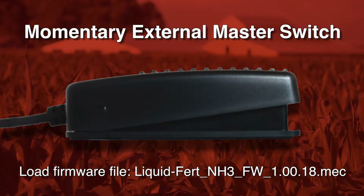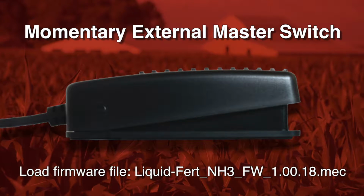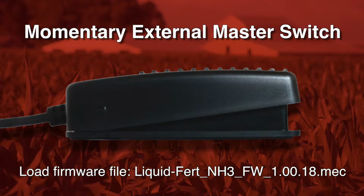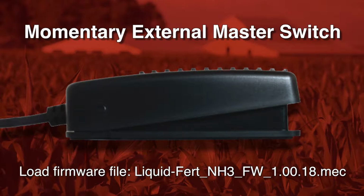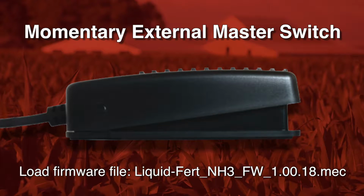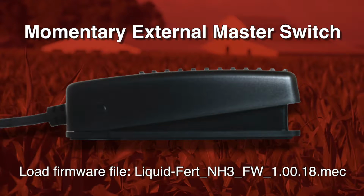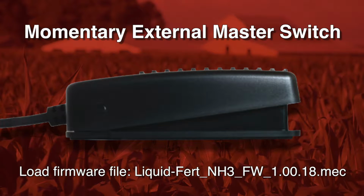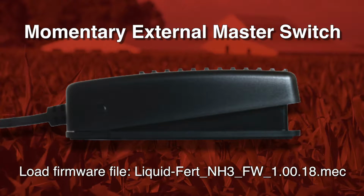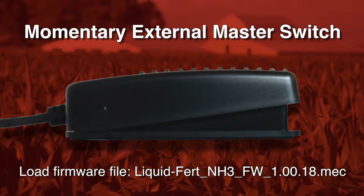If you are going to use a momentary external master switch, as an example a foot pedal switch, you will need to load a different firmware file for your ECU. Please refer to the Download Box Operating Instruction Manual or watch the Download Box Operating video. Both of these resources will provide you with step-by-step instructions to upload the proper firmware for your ECU. The firmware file that you need for the momentary external master switch is seen on the screen.